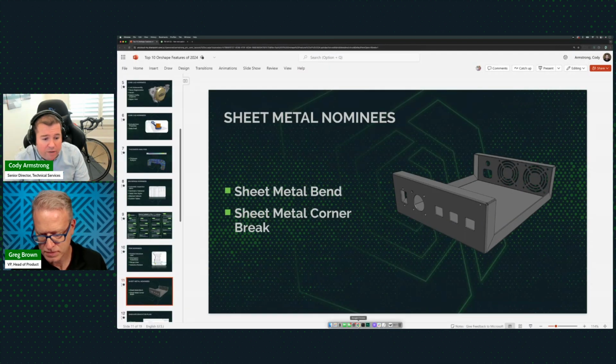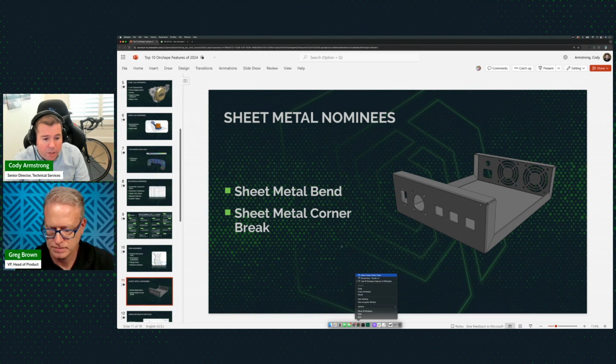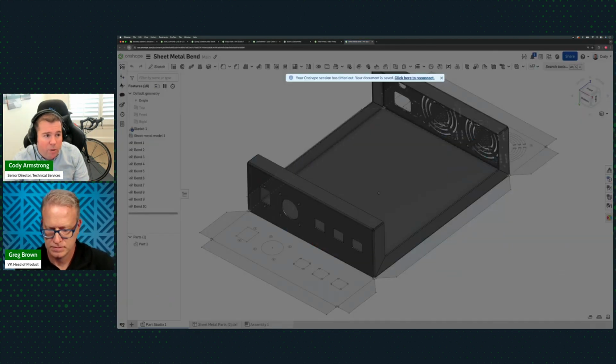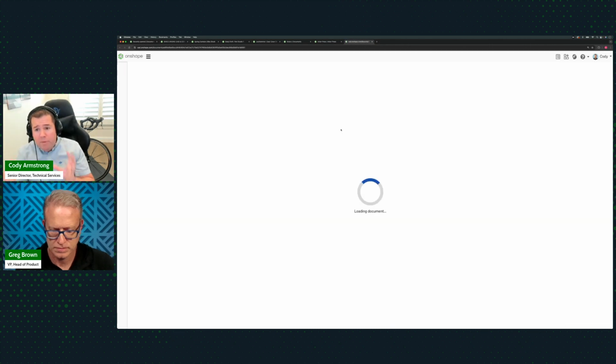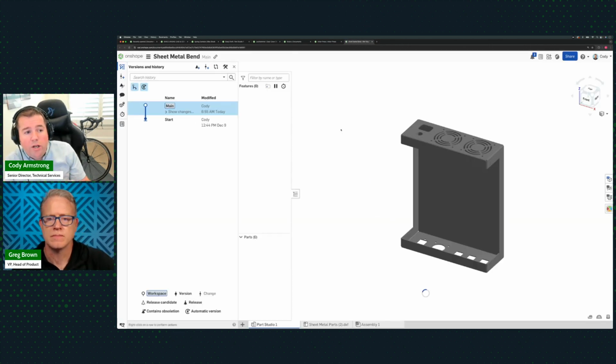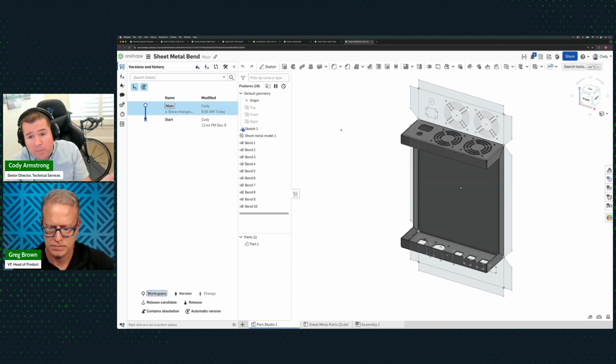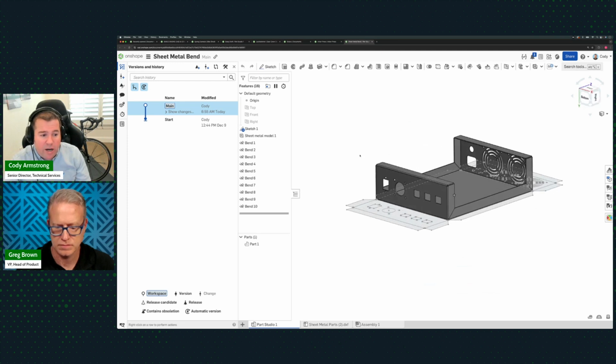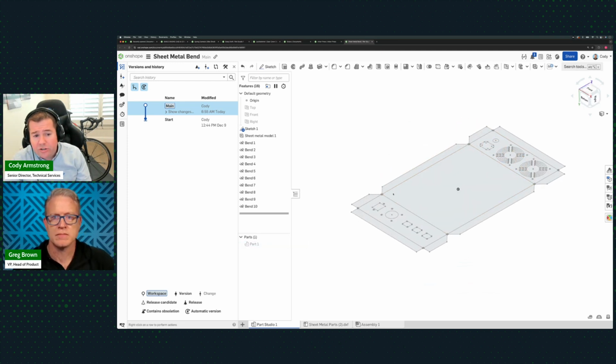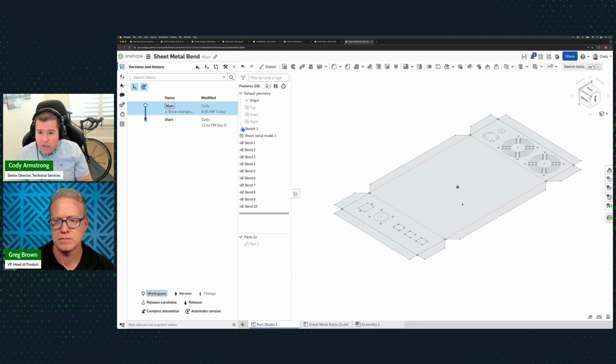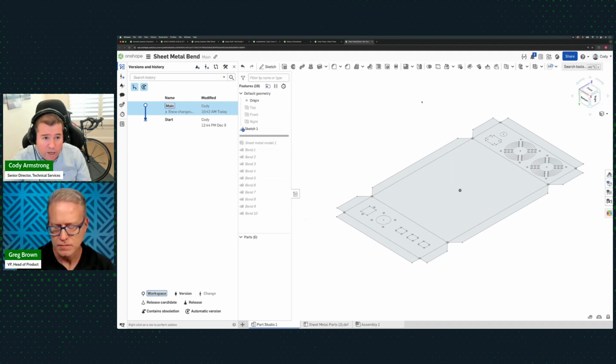All right, so I'm going to dive into this one last time and jump into my sheet metal part. Bear with me for a moment here. And I mentioned this before, but it's really critical when you're working in any kind of flat pattern. Now, there's other applications for it, to be clear. I don't want to stress that it's only useful there. But in this example, I have a sheet metal part that I've bent that essentially started as an imported DXF. And in this situation, I import a DXF with a flat pattern, and then I need to go through and define this as a 3-dimensional model. And so let's roll up and do that. I'm going to roll up to that point where it's just a sketch. I'm going to create a sheet metal model.